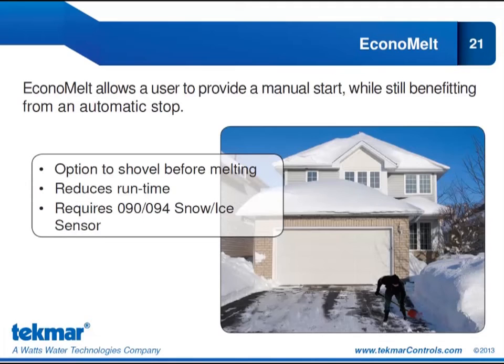And then we're manually starting our system and only running it until that sensor is dry. We're only running it to melt that base layer of snow or ice that mechanical methods cannot remove. So this is another way to reduce the load on the geothermal system if we want to include snowmelt.